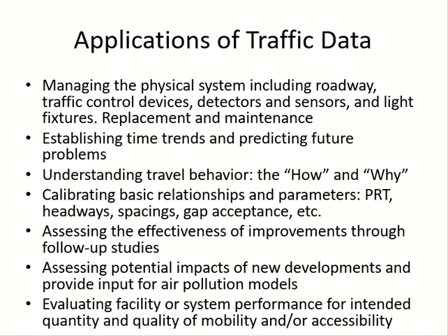Doing follow-up studies. So you made a change on the highway. Then it is your responsibility to see what the effects of this change are. So you change signal timing on the highway, or you change a roundabout to a signal. What happens after that? So you do data collection to see the after effects of a project, of a change. This is called a follow-up study, to see the effects of the changes which you have already made.